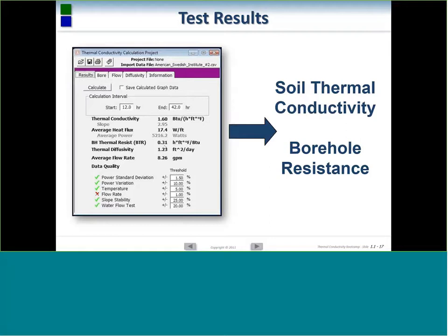The borehole thermal resistance is a number that's extremely easy to manipulate and change because it's based on pipe placement in the borehole, the quality of the grout, and whether there's a water vein that goes through it. There's a lot of different variables that go into borehole thermal resistance. So when you get a borehole thermal resistance value from a conductivity test, it'll normally be slightly lower. In my experience, the reported borehole thermal resistance on the test is slightly lower than what GLD will model from a theoretical basis.